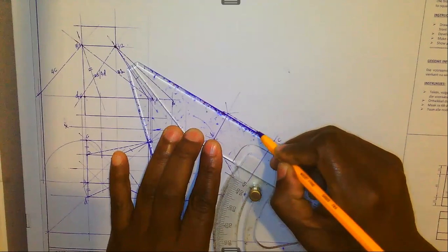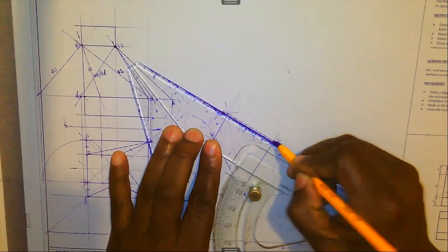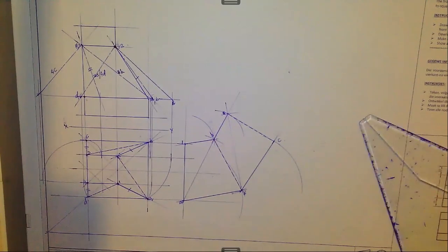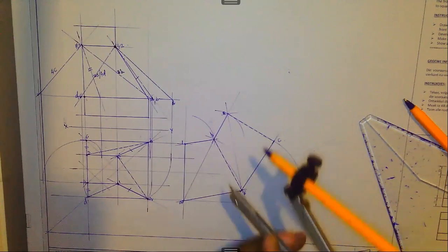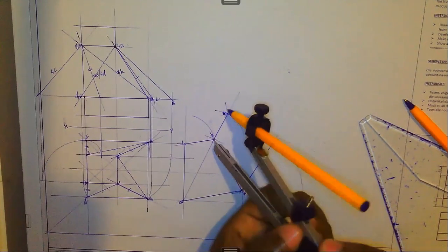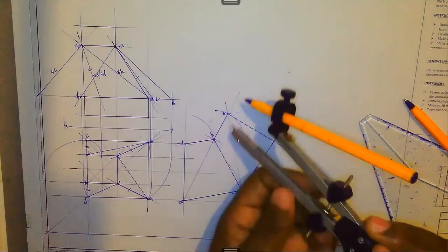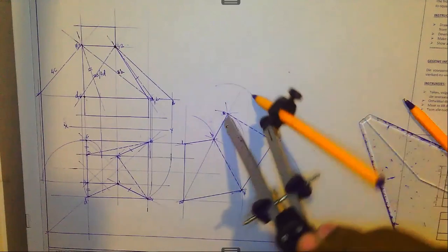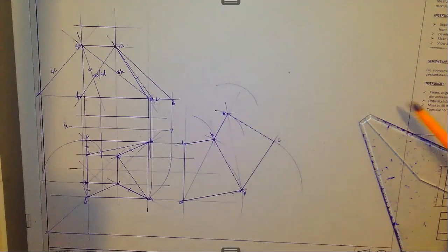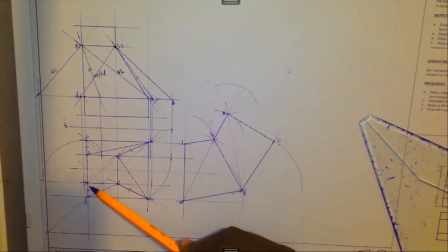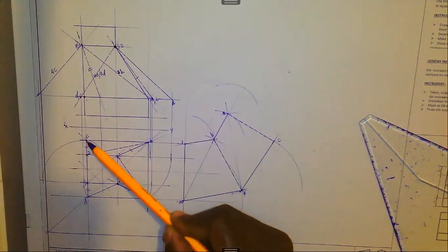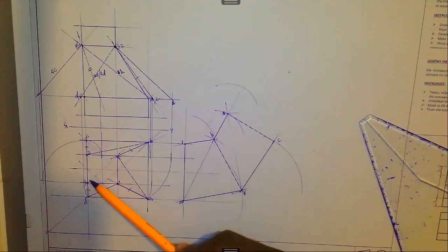There you go. Right. Then from there, we now require point number 4 again, because 1 to 2 and 2 to 3 are basically equal. So you take this distance from here to there, you stand here at point number 3, and you describe an arc like that. You now require 3 to 4, which is the true length from here to there. C to 4 is the true length which we defined like that.